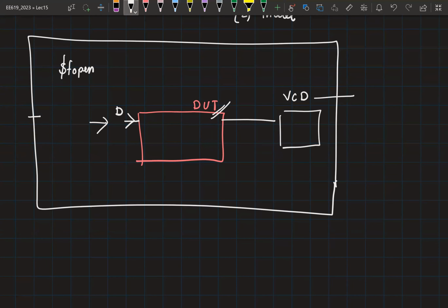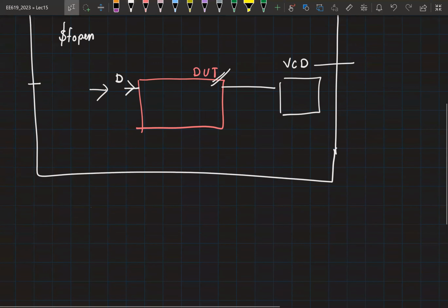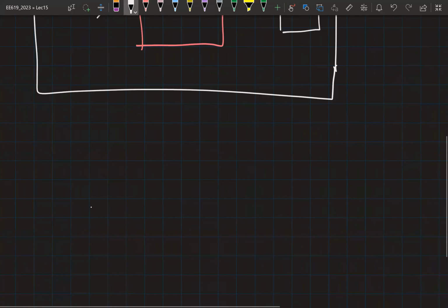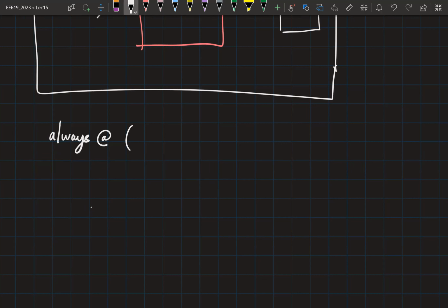One more comment I want to make is, the test bench, you can't make it synthesizable. I mean, there is no reason to try and make it synthesizable, right? So when you are writing synthesizable code, there are certain things that you have to keep in mind. For example, let's say you have an always block. Within this always block, you can't be using both blocking as well as non-blocking statements. Within one particular always block, you have to stick to one form of assignment,